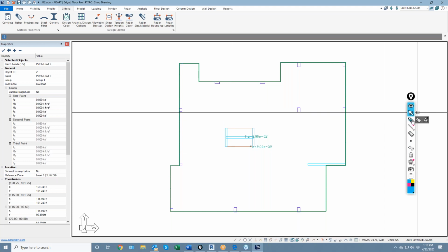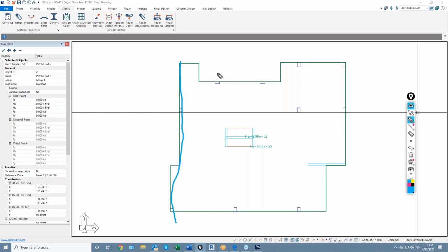Technically, if you wanted to, you could say, well, I'm just going to represent both directions in the program. Remember, it's just a model used to simulate the slab. So you could then take the information from the model and portray it however you want in your drawings, as long as it's compatible with the actual solution. So in this case, we're going to say that the Y direction is the banded tendon direction. So we're going to have tendons that do something like this.